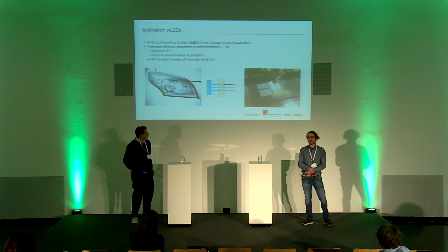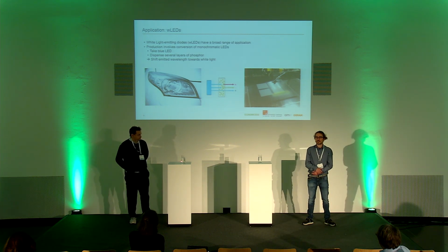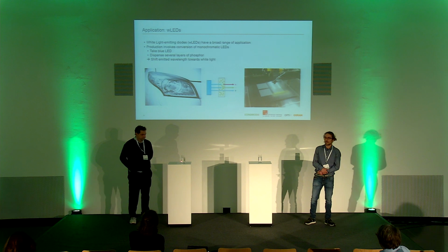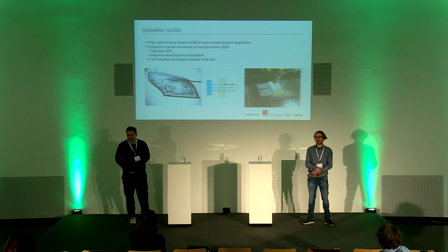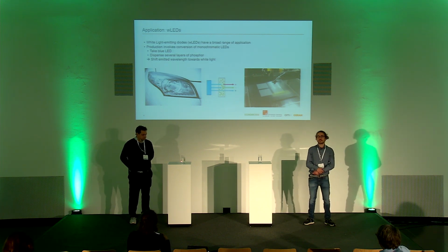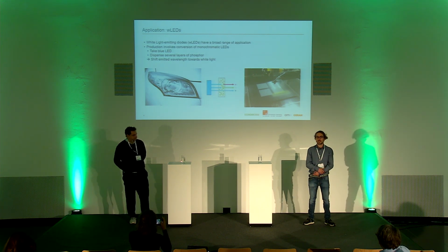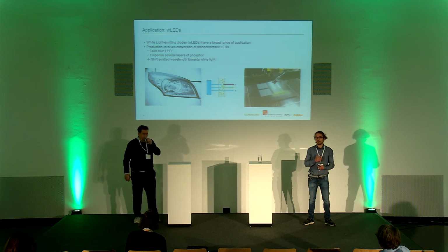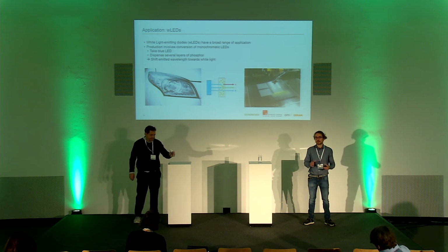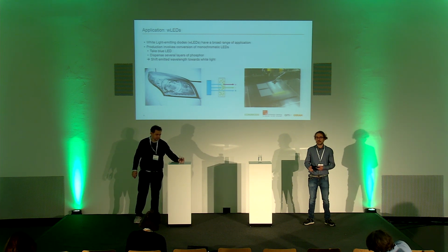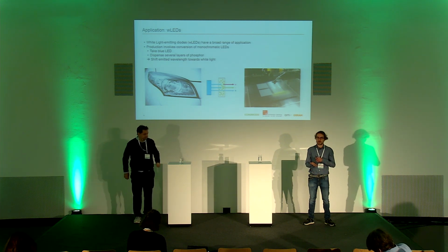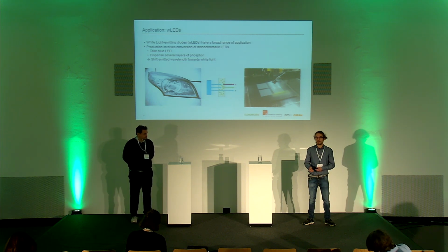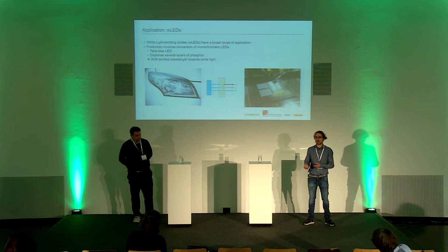So most of the time at AMS-Osram, we are not concerned with the mass production of cookies. We actually manufacture, for example, white light emitting diodes. And on the left, you can see one application of white light emitting diodes. It's this classical automotive headlamp. And how do you do it? You start with a blue light emitting ground substrate. And upon this ground substrate, you deposit a phosphor conversion layer. And this has the effect that the blue light is shifted into the white light region.